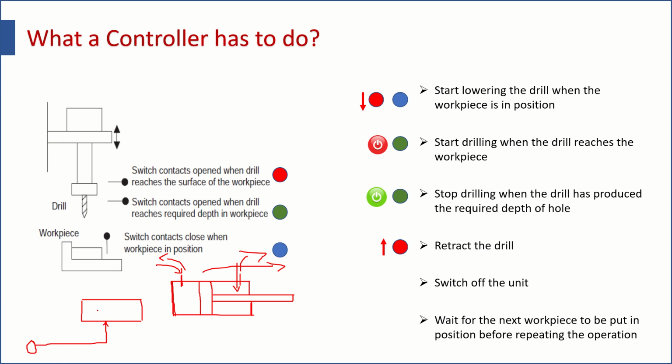Now if you control this valve in a particular manner, then on the first cycle air will enter from the compressor into this chamber and the piston will go forward. When you change the condition of this valve, this particular channel will be connected to the compressor. So under the first cycle, the compressor will press the piston so that it extends, and in the other cycle the air will be allowed to enter through this cavity so that the piston makes a retracting motion.